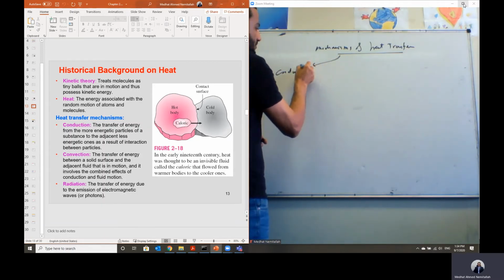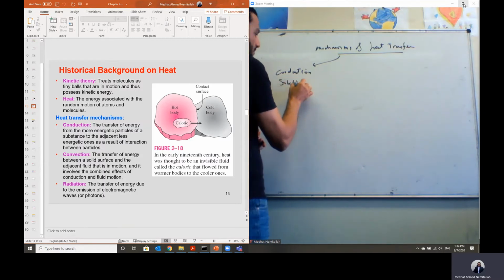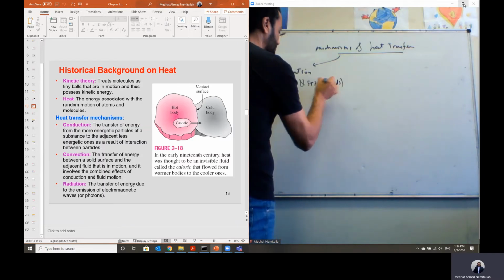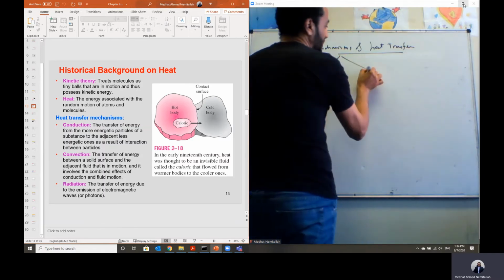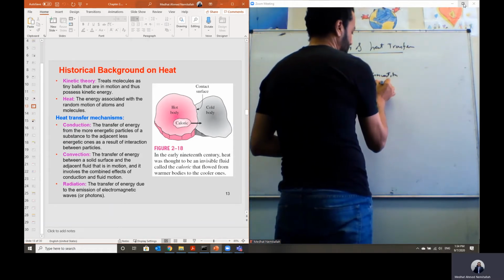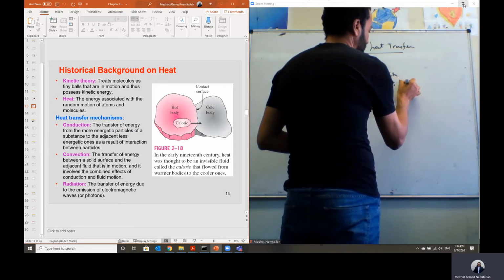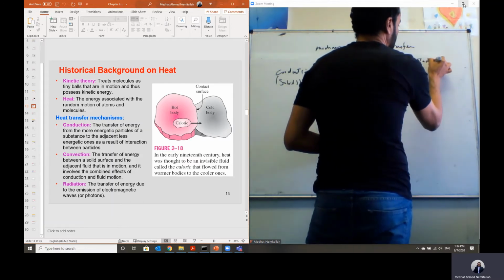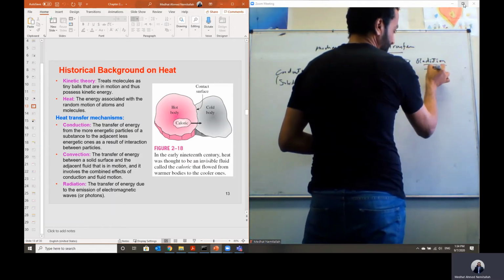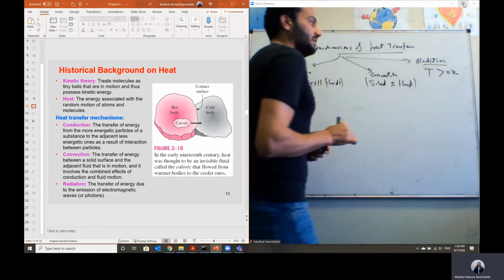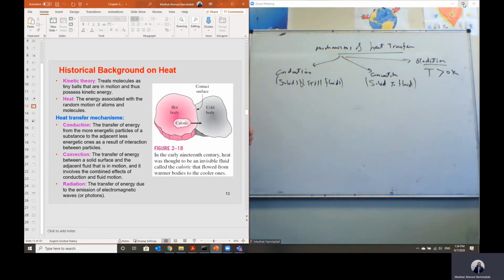Heat can transfer by conduction in solids and still fluids, not moving fluid. Heat can transfer by convection from a solid to the fluid body around it. And heat can transfer by radiation: any body existing at a temperature greater than absolute zero Kelvin can emit heat by radiation to another body existing at a lower temperature. Okay, but let's consider each mechanism.